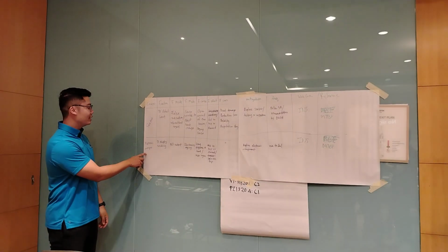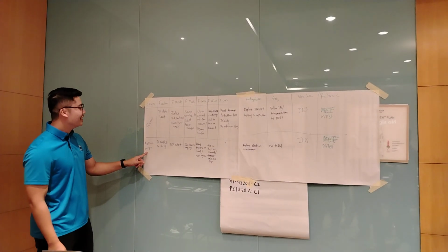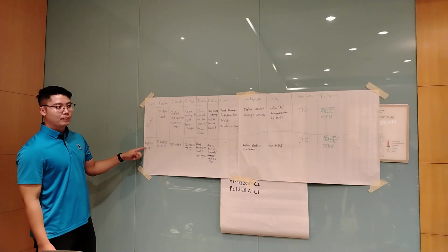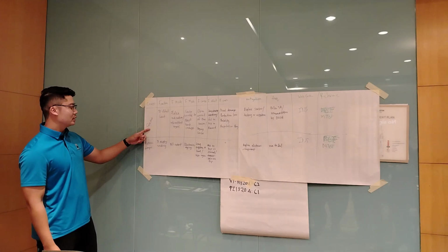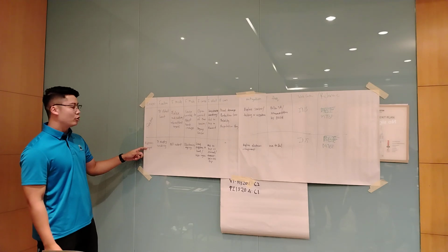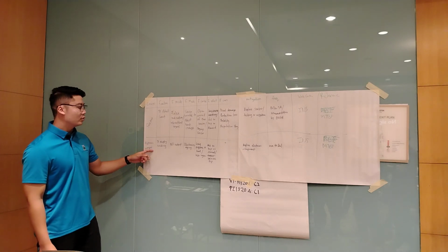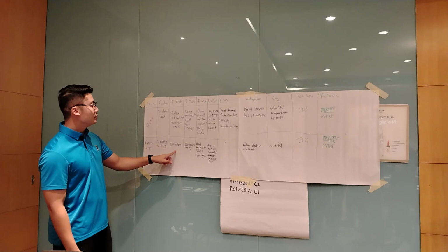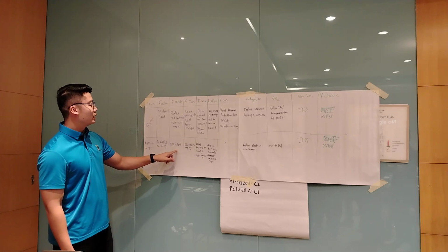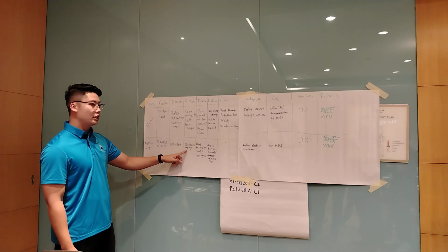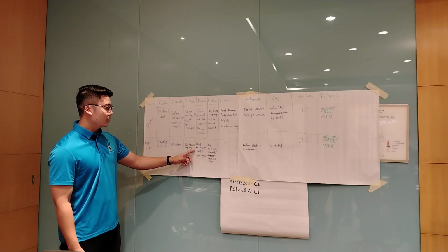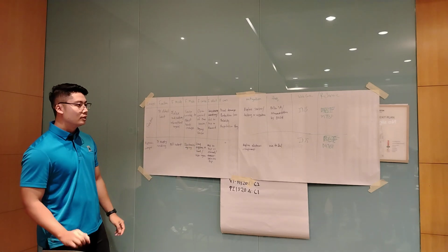Thank you. The component is an electronic component. The function is to display reading. Because we receive input from our sensor, and then our electronic component will convert it to output and send to our RSS. So for the failure mode, no output. The failure mechanism, what basically leads to this no output, is electronic aging. The failure cause is long exposure to heat or water ingress.